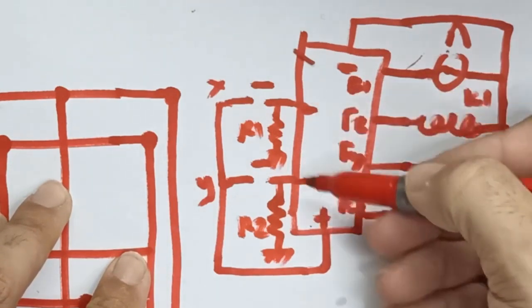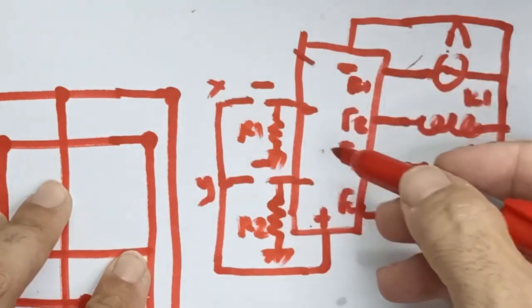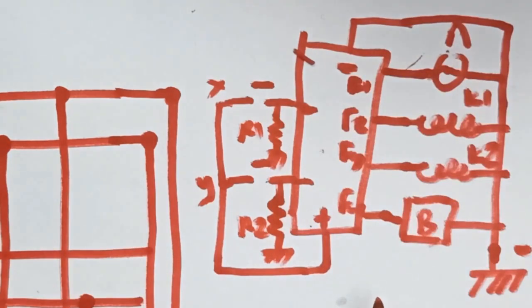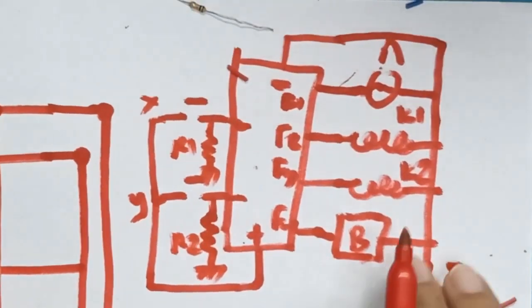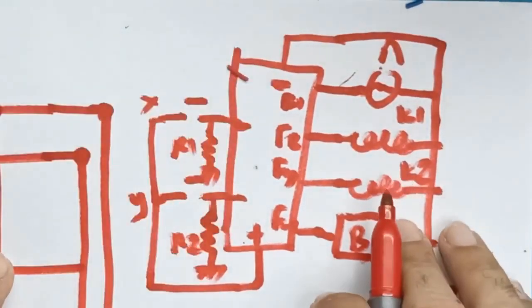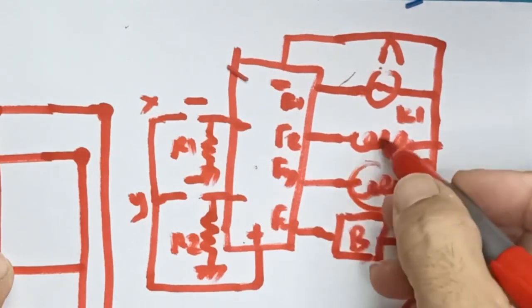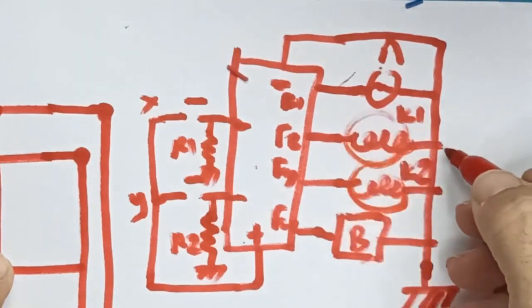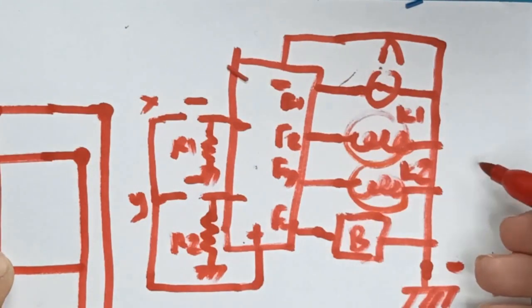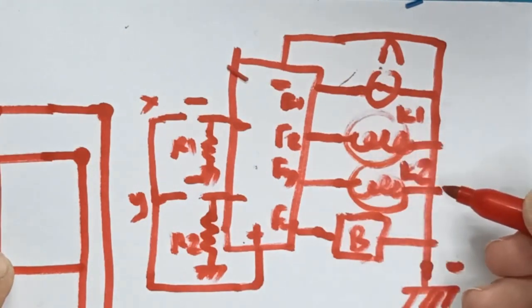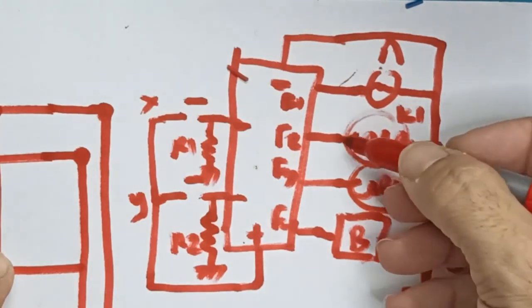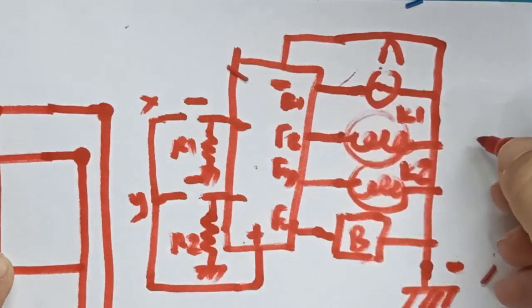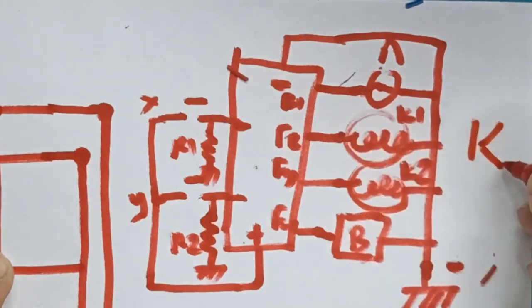And the second issue is with the outputs. I can't connect components that pull a lot of current directly. The relays won't work like this, as I have connected them here. The LED is okay, and the buzzer will work too, because they are small, but the relays won't work like this. As I have connected something to the output, I will need to put transistors in between.